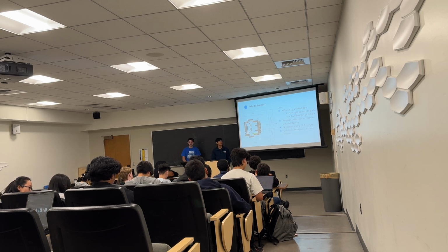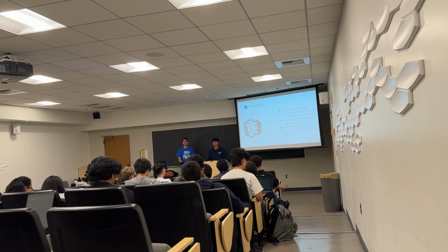Okay, so some bad things about our sensors. Probably the biggest is that ambient light can greatly affect it, and the worst culprit is probably the sun, because the sun emits a ton of infrared light. So our Micromouse is not going to work very well outside or in places where there are a lot of windows.